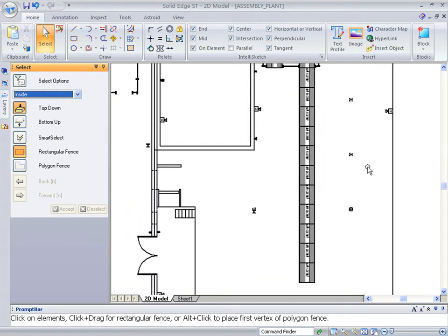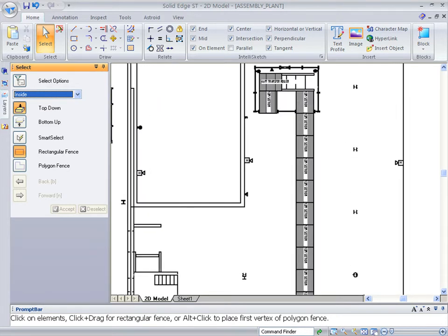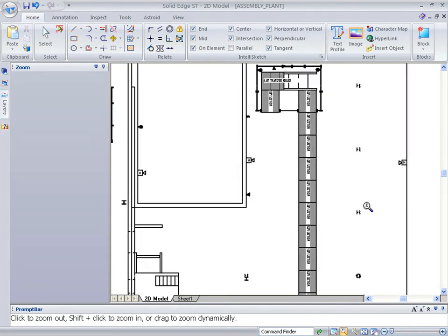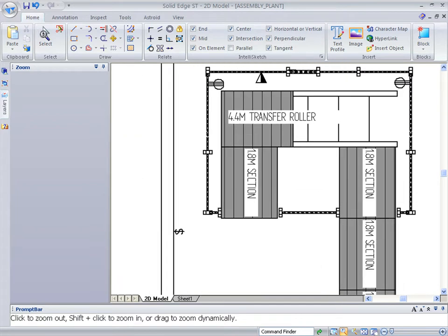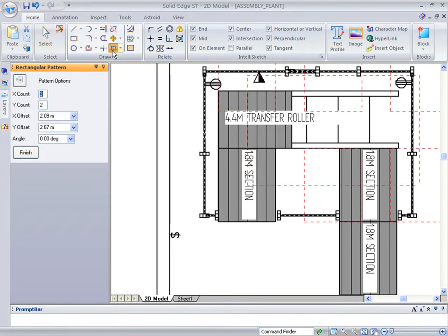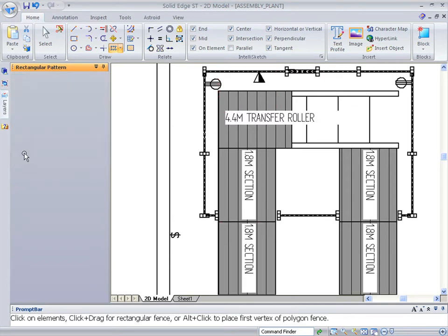On this right side, we use 12 conveyors. As you can see on the left side, we only need about half as many conveyors. So it looks like the instance count we'll need is 6. So we're going to run the command again, and notice that we have a most recently used values field to make this go a little bit faster. In this case, we're going to place, again, the 6 blocks on the left.